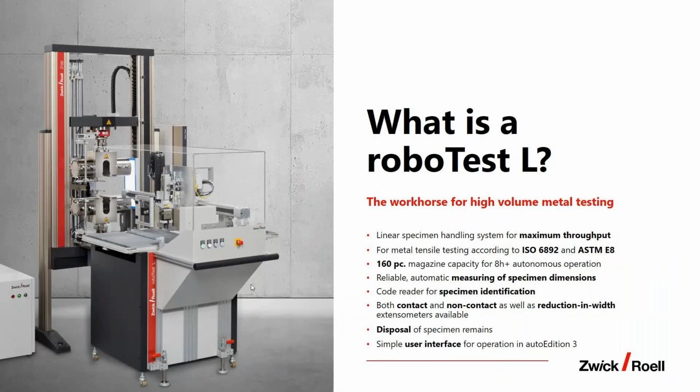Next package, this is now metals, roboTest L. L means we have a linear axis here, that's why it's called L. And we have a moving table as a second axis. So here the focus is clearly on a workhorse for metals testing. The typical ISO 6892 and ASTM E8 are fully matched.